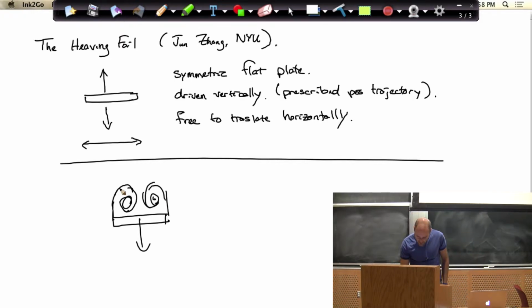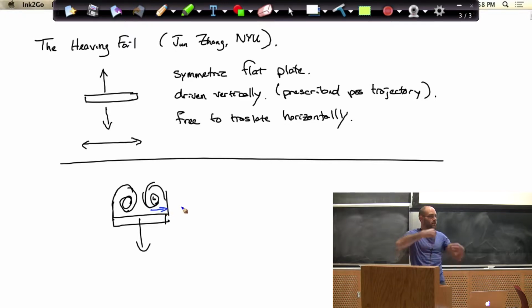And so the water's spinning around like this. And the dynamics of the plate in the horizontal plane are governed by the water shooting this way, so it's pushing, by just friction with the water, it's pushing it this way and it's pushing it this way. Okay, so there are these balancing forces on the plate from the spinning fluid, okay? And they're symmetric and opposing, until something happens, right? Something's a little bit imperfect, something's a little asymmetric, because there's going to be some imperfections. This is going to be an unstable fixed point, okay? It's just like our pendulum balancing at the top.